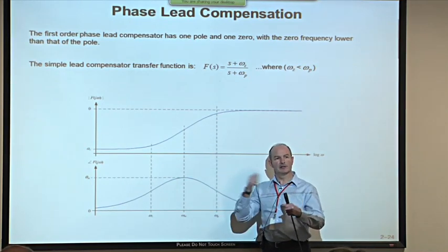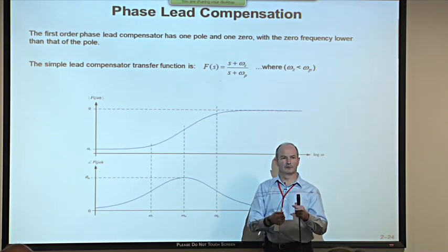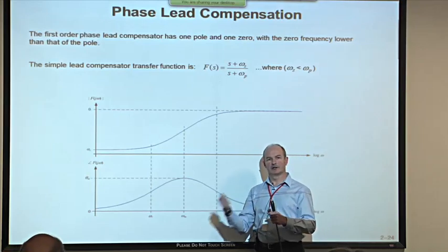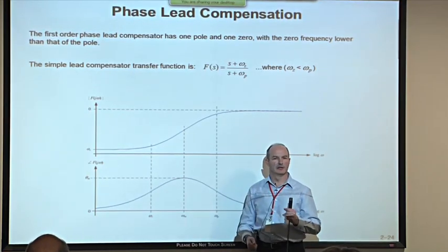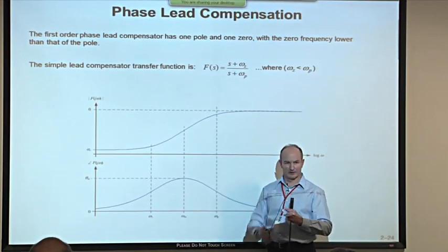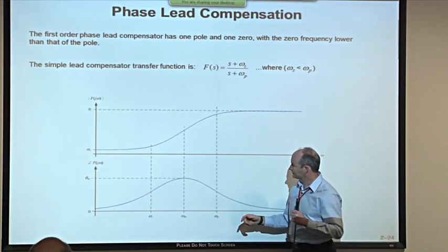So it tends to be an iterative process. You design the compensator you think you want, and then you find that there's a mistake. So you go back and do it again, and you iterate progressively towards an optimal kind of design. I'll show you this in the tutorial very shortly.